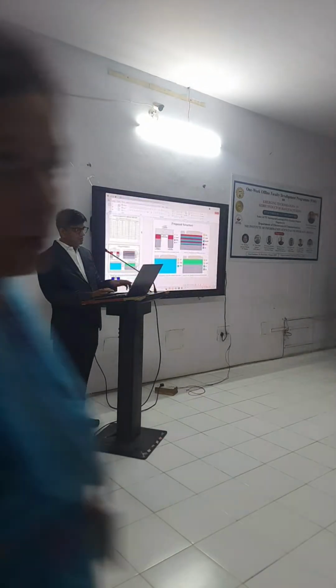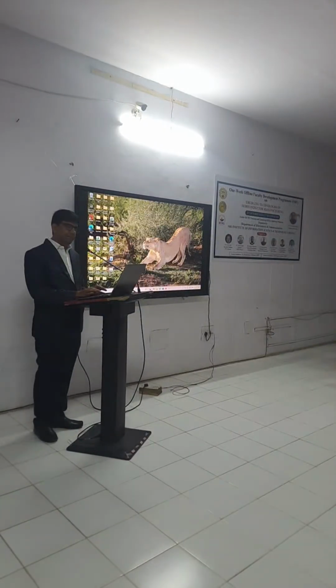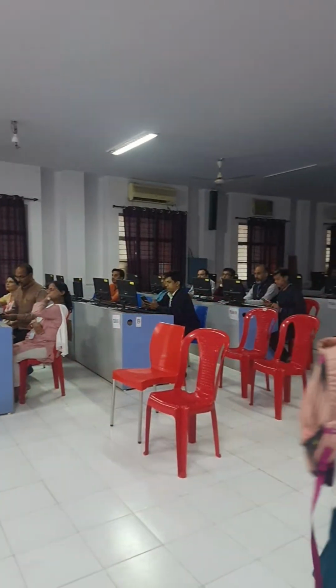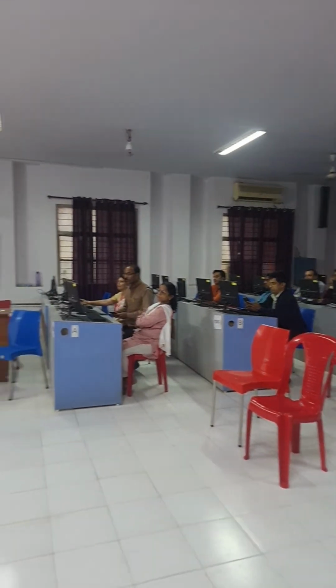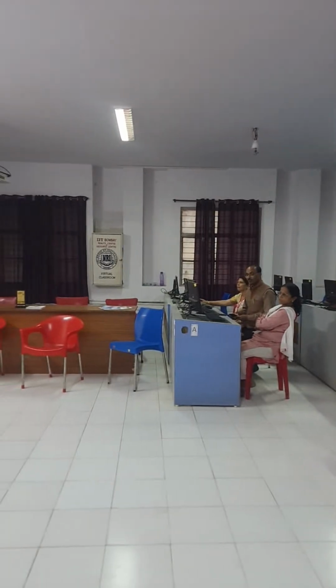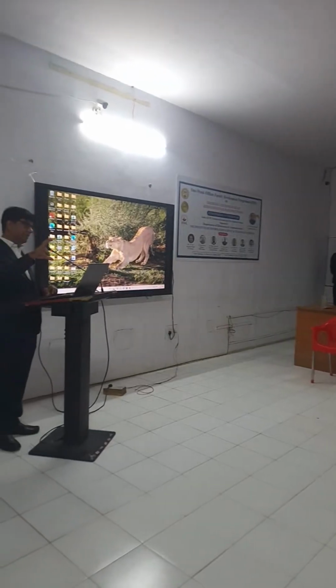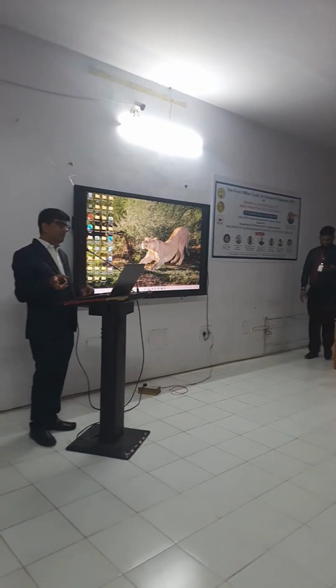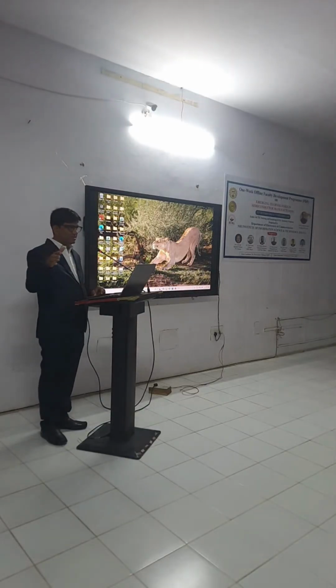So in this form of simulation process, we have a 3-step. One, geometry design. How do we design the geometry? Once we design the geometry, then we have to define the material, meaning for which layer, which material you require, you will define the material. And after that we will provide a boundary condition, meaning where we have to fix the boundary, where you have to apply a perfect matching layer, where you have to apply the signal.